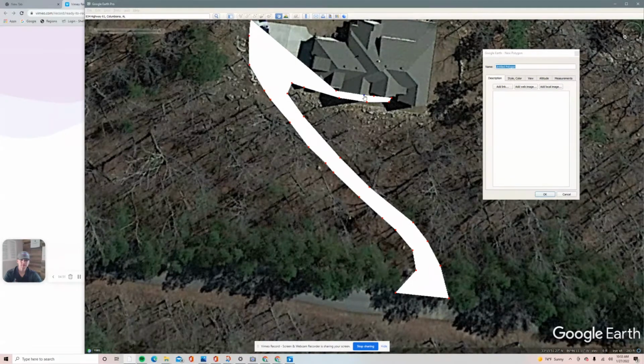So we're going to make this a little wider here. And then, all right, so say I've got to go back on a point and fix it, make it a little wider like I just did that one. So after you do that, if I click right here, it's going to pull the polygon from there to there and it's going to mess it up like that. So what you actually have to do is click on the last one here and then you can start clicking again.